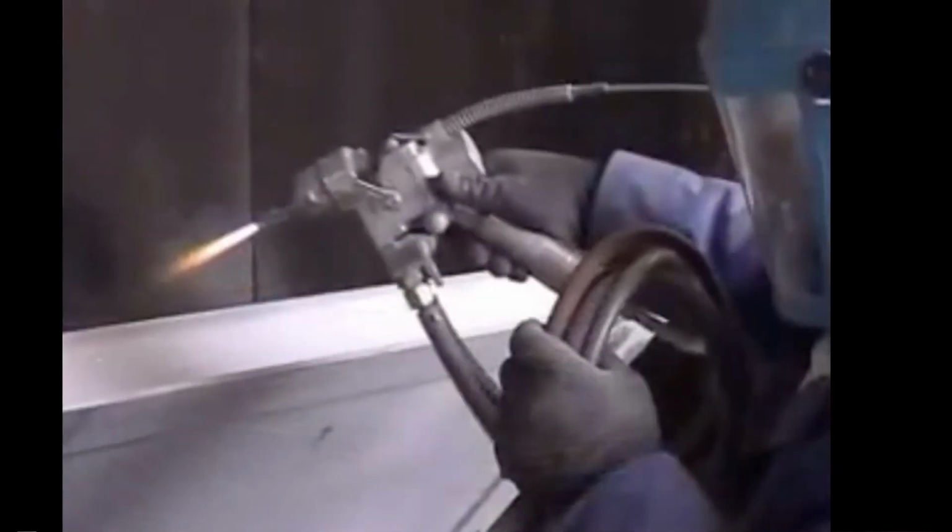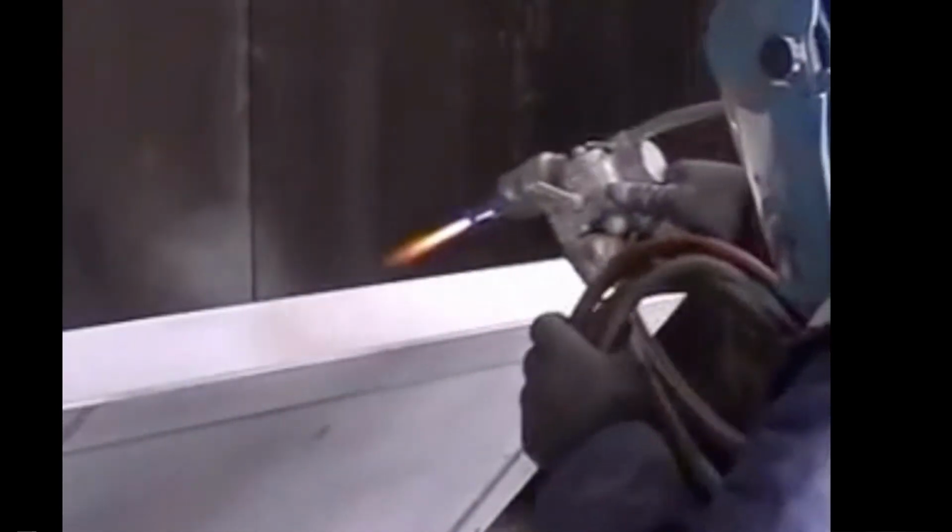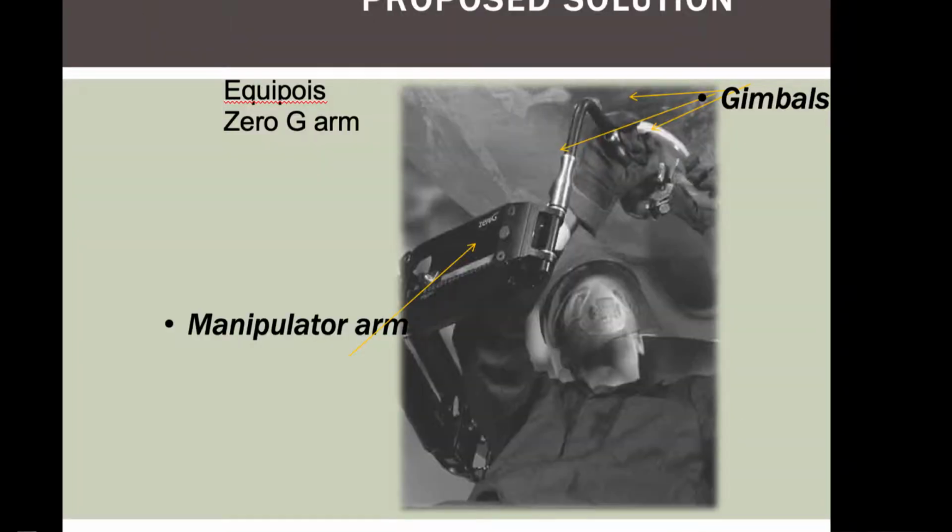So there was a lot of resistance when they were feeding the wire through, and that's why they would have it up over their shoulder. And that was the harder thing to fix as far as using this ergonomic solution, was how to get that wire to feed through, because the rate at which it was fed is important if you need to lay down the material at a certain thickness.